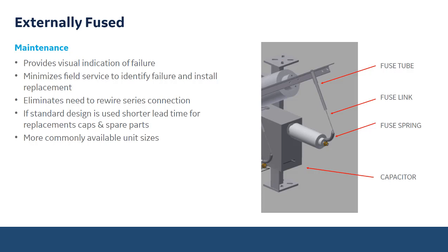Also, the externally fused, if the standard unit design is used, has a shorter lead time for the replacement caps, and spare parts are available, and most commonly available unit sizes are for the externally fused. And so you see, there's a lot of benefits of ordering a standardized system if you can.